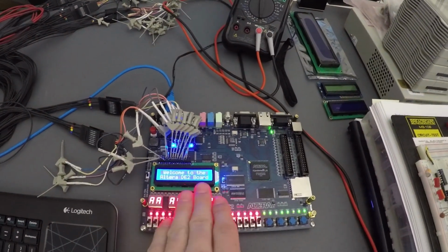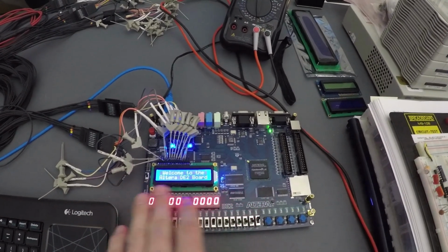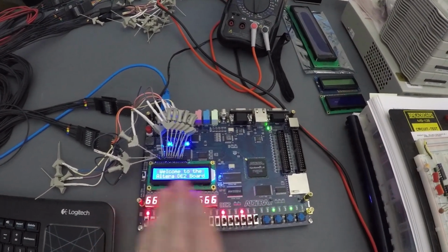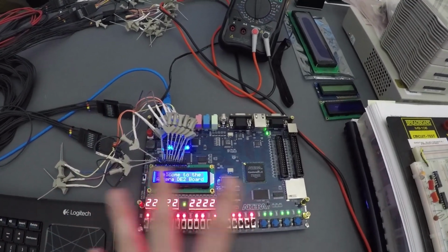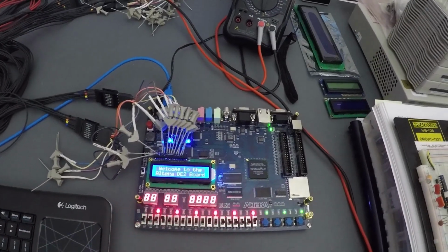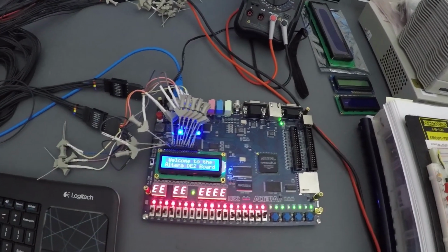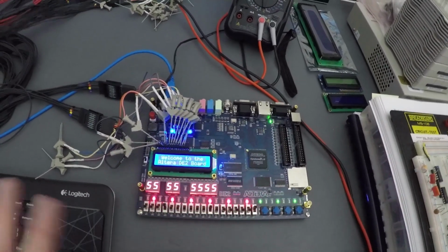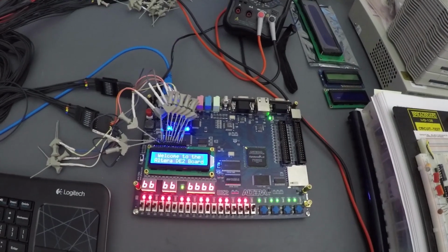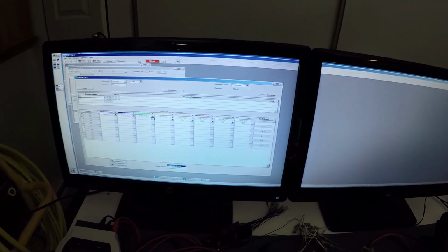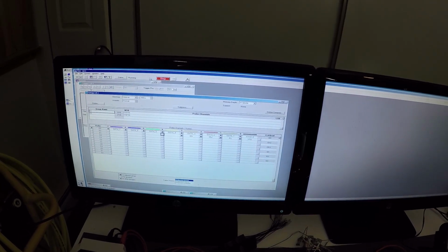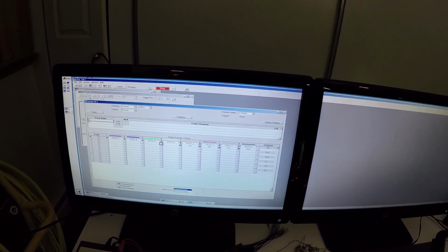And because our Altera default display here has run through its sequence already, because I powered it up beforehand, there's no values being shown or being read on that 8-bit databus. So it hasn't been able to see any value there, and that's why it's continuing to loop in its run sequence, constantly capturing, waiting for that hex value of 38.